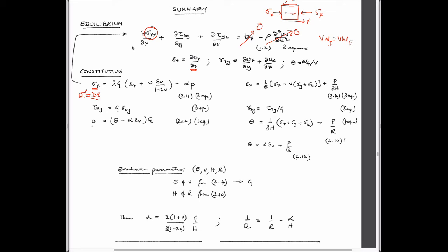So four requirements. Equilibrium equation, the top equation on that page. Constitutive equation, this equation here. Displacement should be continuous, which is a requirement, and we have initial conditions and boundary conditions to solve it. So this is the conservation equation, equilibrium in this particular case. This is the constitutive equation.